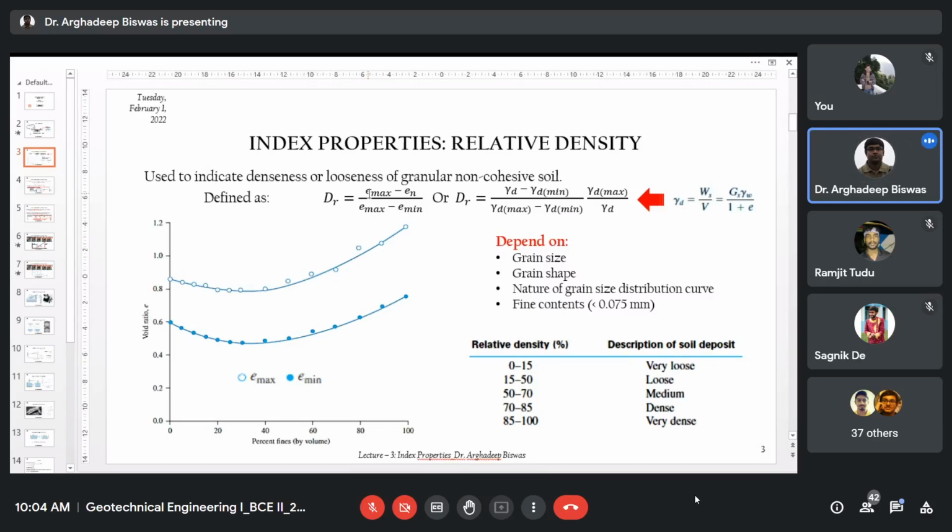Okay, so that kind of protrusion will be used in case of clay type of soil. If you want to roll some sandy soil, then the vibration technique is used, that means the roller drum will have a vibrator inside, and the entire rolling system will be accompanied with mass as well as vibration. That is a vibrating kind of roller, which is mostly applicable in case of sandy soil. You must have seen some road roller, or the rolling system which we use to compact our cricket, what is that, pitch, right? So these are the rollers or compactors that will be used to roll or compact our field, that is soil, to increase the density or to decrease the void ratio.